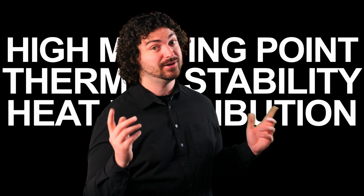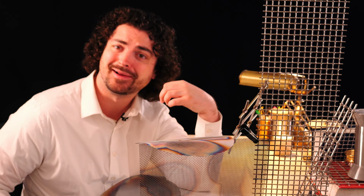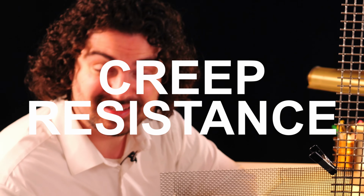Speaking of high temperatures, if things are heating up, what will your mesh do? Hopefully have a high melting point, great thermal stability, great heat distribution, and creep resistance. What are those? Oh, hey, didn't see you there. So a high melting point is pretty self-explanatory. At extreme high temperatures, you want a high melting point for your mesh so it doesn't literally melt. And thermal stability is all about maintaining its strength even when those processes get a little heated. Heat distribution is when your mesh distributes the heat evenly throughout it, which makes it way less likely for breaks to happen or deformation in very specific areas. And creep resistance is kind of like the beginning stages of melting, but it doesn't melt all the way.